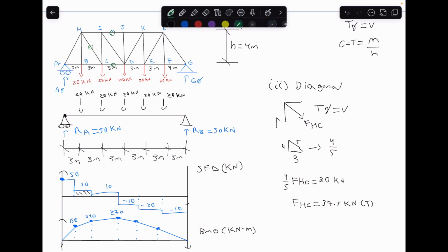And that's basically it. You just keep going from there until it's solvable using method of joints or method of sections. And by the way, a lot of these questions are symmetrical, right? You get a symmetrical truss. So the magnitude in this guy is going to be the same as in this guy, right? And then the magnitude of the chord forces here are going to be the same on the other side. They both use the exact same bending moment, right? So it's actually very simple to make it determinate, and then you're going to use method of joints, method of sections, starting at one of the supports, and go from there and solve it.